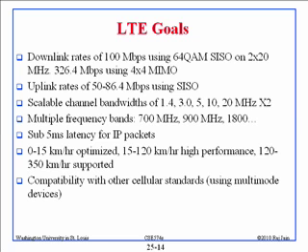So anyway, then the mobility wise, this is optimized for 0 to 15 kilometers, high performance up to 120 kilometers, and it will just work barely at up to 350 kilometers. After 350 kilometers, the performance is not guaranteed, working is not guaranteed. So can anybody guess as to what happens at high speed, what goes wrong? Doppler effect. And what does Doppler do to OFDMA? Each carrier frequency changes. Basically, you have the carrier here, and if you are moving, the carrier looks like over here, right? So it can overlap the other carrier, right? So there is inter-carrier interference.